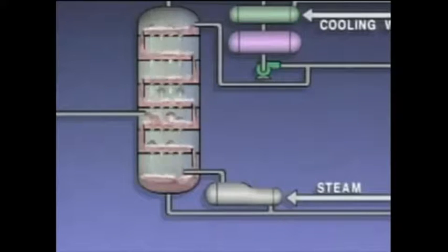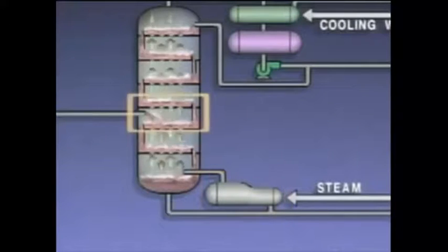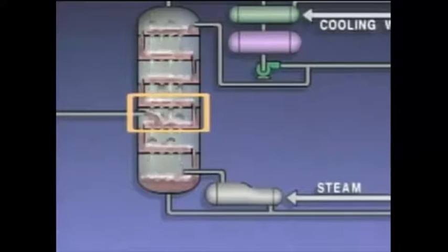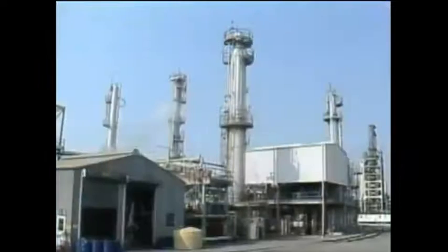Some distillation towers operate at a low pressure. In these towers, a tremendous volume of vapors may be produced, so the diameter of the tower must be large to handle the vapor volume. Since a lower volume of vapors will be produced in a distillation tower that operates at a high pressure, the diameter of the tower can be relatively small.